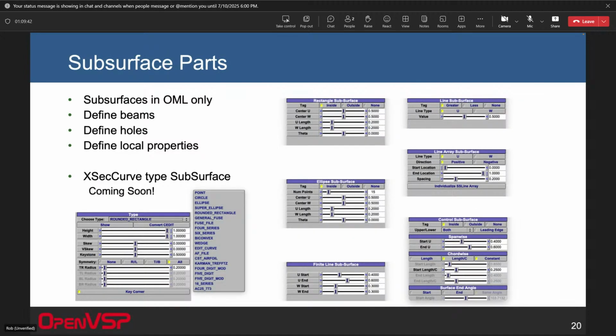So we also have the ability to do what we call subsurface parts. Just like subsurfaces in the main OpenVSP, we can define subsurfaces in structures. And we draw those subsurfaces on the OML of the component. And you can use those to define beam elements around the boundary of that subsurface. You can also use it to define a hole. You can say, draw something for a landing gear cutout and then delete the elements on the interior of that to create a hole in the skin for the landing gear.